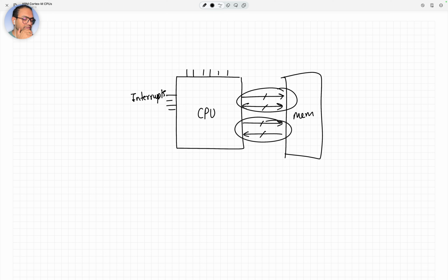And listen very carefully to what follows. If your system were to have 128 interrupts, let's say, your CPU is attending to some signal that's coming from the engine. It's attending to some signal coming from, I don't know, some buttons in the car. Maybe it's sensing the temperature in the car and so on. And all of those are supposed to be interrupts.